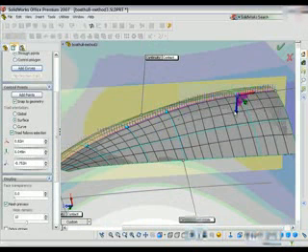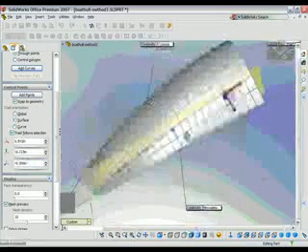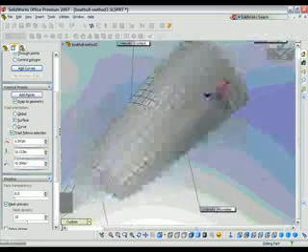I can also use our property manager over here that has thumb wheels to control these vectors for the triad. This gives you much more precise control. I can use my Alt key to halve the value as I twirl the knob, and then the Control key to double that value.